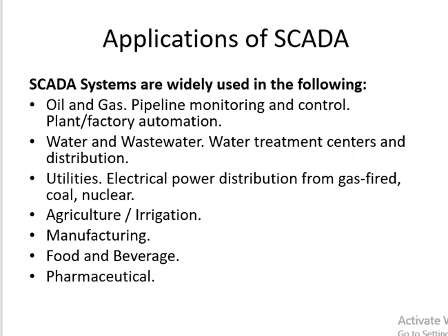There are many kinds of RFID, each with different properties, but perhaps the most fascinating aspect of RFID technology is that most RFID tags have neither an electric plug nor a battery. Instead, all of the energy needed to operate them is supplied in the form of radio waves by RFID readers. This technology is called passive RFID to distinguish it from the less common active RFID, in which there is a power source on the tag.